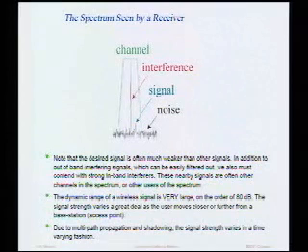The other issue with just using an amplifier is noise. In many situations, the signal is not much bigger than the noise. And so if we just go into 140 and just basically design an amplifier, you'll find out that it might actually be a noise amplifier. It might actually make the noise bigger than the signal that you're trying to amplify. So pretty soon, the signal that you're trying to detect is lost in the noise. And this noise is something that's ever present. We can't get rid of it. It's a part of nature. It's a very natural phenomenon.